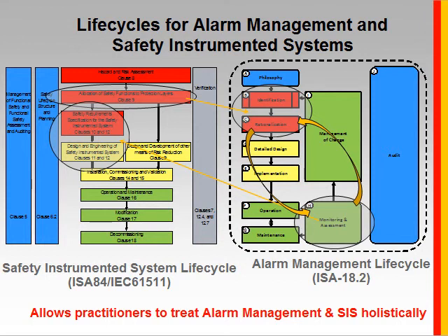One of the other significant things of this standard is that for the first time, the discipline of alarm management now has a standard that's comparable and can be laid alongside the functional safety standard, the standard that's been around for a lot longer and is very well established. When we do this, one of the things that we see is these standards, these life cycles, are very similar and very comparable, and in fact they also interconnect in a lot of their stages, which leads one to think that this would probably make sense to treat these two disciplines or these two processes from a holistic point of view.